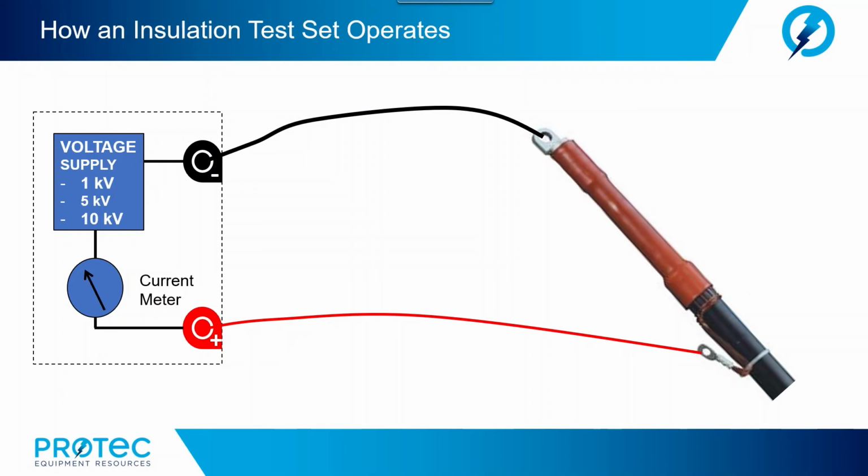An insulation resistance tester is essentially a high-range resistance meter or ohm meter with its own built-in DC generator. The instrument's generator, which can be hand-cranked, battery, or line-operated, develops a high DC voltage that causes several small currents to flow through and over surfaces of the insulation being tested. The total current is measured by the ohm meter, which has an analog indicating scale, a digital readout, or in many cases, both an analog and a digital readout.